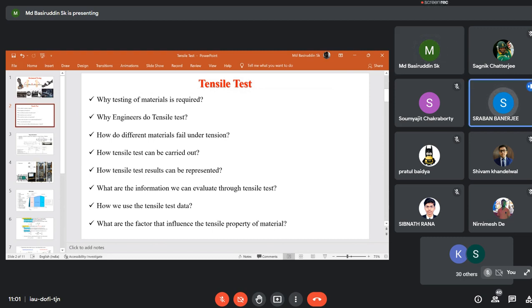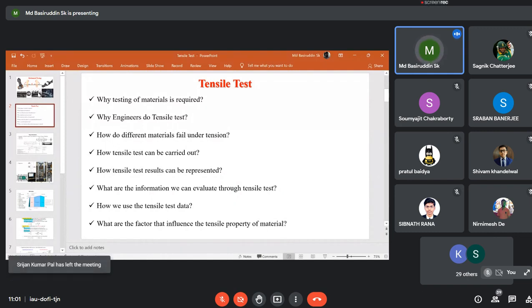These industrial standards, industrial tolerance standards. Industrial standard, or the ASTM standard, or Indian standard that you need to follow to fabricate the specimen. And of course, based on your machine capability, you need to follow a certain specific standard. Like if you have very thin flat samples or thin flat plate, in that particular case you may not be able to fabricate the solid cylindrical specimen. You need to follow a certain standard where the flat specimen is specified.